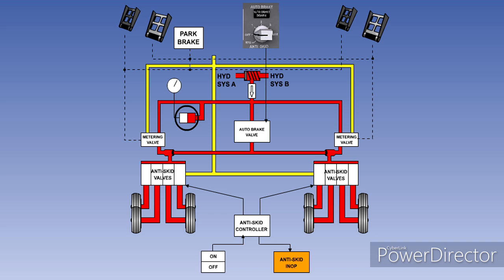However, if normal system pressure is lost and the brakes are operated, the accumulator pressure will fall until all fluid in it is used up. The gauge will then read the gas pre-charge pressure. The non-return valve will prevent backflow to the pumps. In some systems, the accumulator has sufficient fluid to stop the aircraft from high speed, but in others, it only has sufficient fluid to maintain the parking brake overnight.